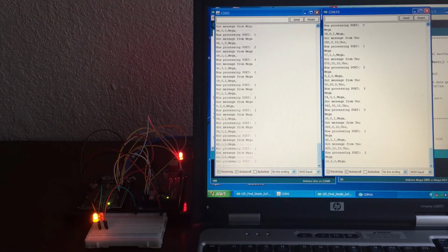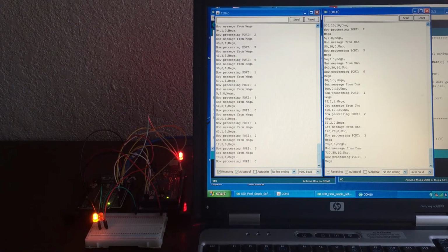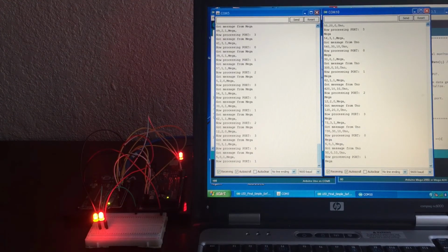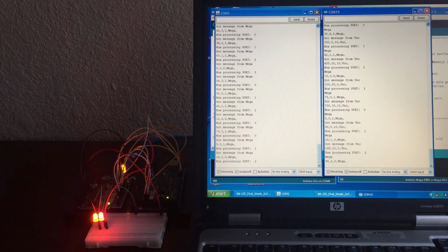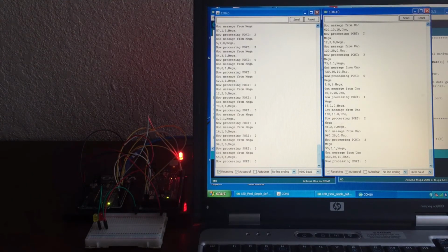Now, some of the tricks that you want to keep in mind. One, I would recommend using the parseInt to read in integers or numeric values. Have characters and strings at the end of the data string if possible. The second thing I would suggest is separate data by commas, then read the data string until -1. And if you read a comma, then ignore it.